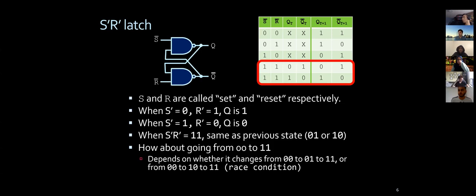Yeah, the Qt axis in Qt and not Qt means that it's really undefined, because it really depends on what was in the circuit before, right? Like we don't know what Qt was at the beginning. If we never used this circuit and there was no power there before, the state there is undefined, right? We didn't set it to anything ourselves. So at the time t, when we start to use that, there's only input here, but this output is not defined yet. So x means undefined.